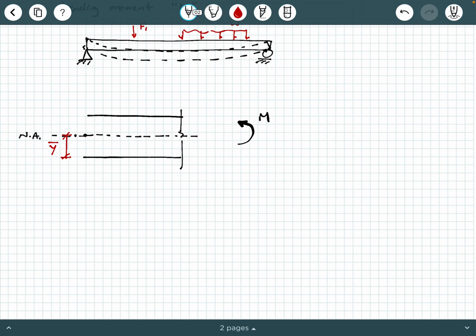Now specifically, I'm going to call this Y bar sub B for bottom. You remember from your previous knowledge from statics, you could also define it up at the top as Y bar, but we would call this Y bar sub T for top. And that just means that this Y bar is measured from the top surface, and this little b right here just means that Y bar is measured from the bottom surface. That's all that means. And you remember how to get centroid from previous knowledge.